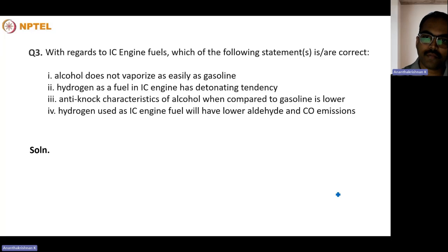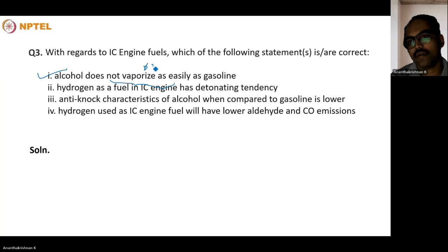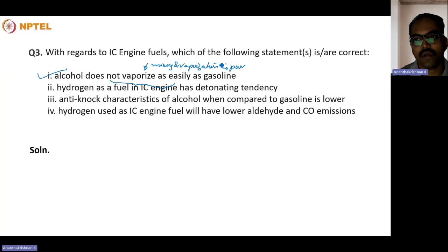So the first part of the problem, alcohol does not vaporize as easily as gasoline. That is absolutely right. They had tried running alcohol on SI engines, but the reason it's not so popular is because for the same stoichiometric ratio, we will require twice the volume of alcohol compared to gasoline to give the same power. And it does not vaporize easily. The mixing and vaporization is poor for alcohol compared to gasoline.